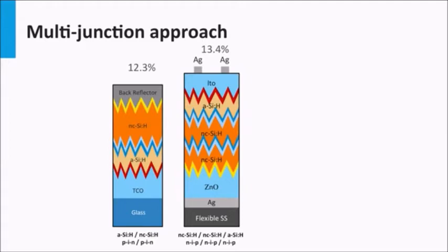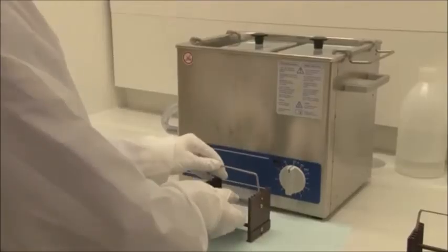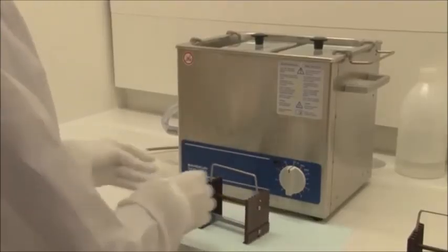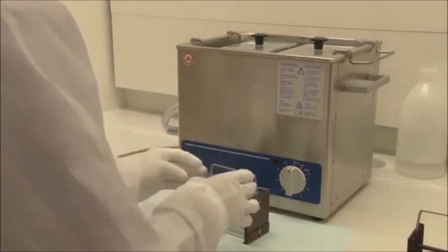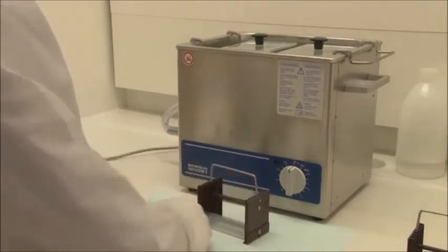Nowadays, doped nanocrystalline silicon oxide layers are used as intermediate reflective layers. They have the bifunctionality of generating the built-in field over the absorber layers and acting as transparent intermediate reflective layers. Let's go to the DIMES lab at the Delft University of Technology. We will show how thin film silicon solar cells are made on lab scale.